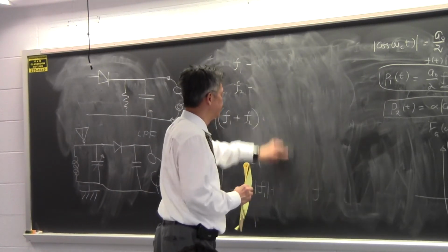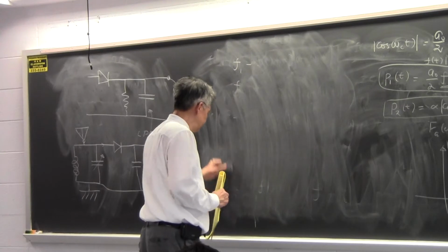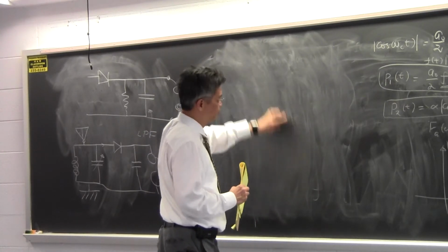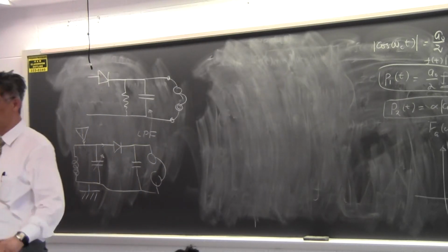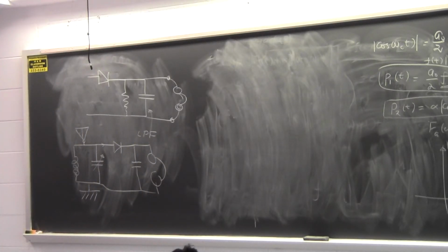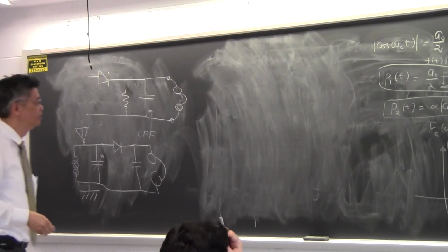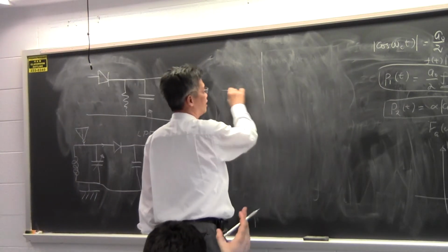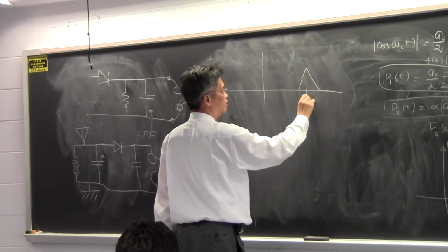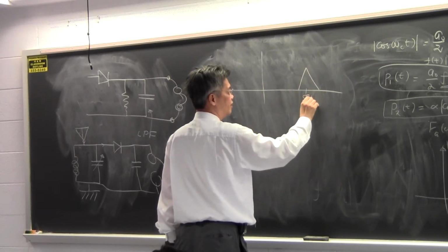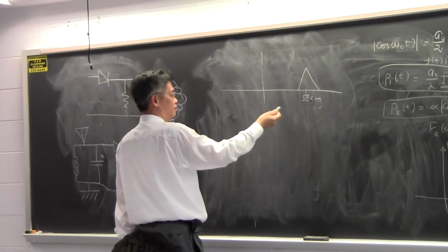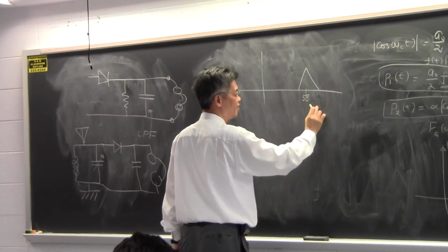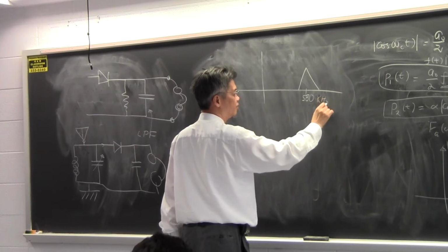If you do coherent detection, you can bring the signal back into the pass band as a low frequency band, but in order to get the signal properly passing through your system, you still need a very high quality filter. So if I have AM580 over here, 580 kilohertz, that means the carrier of the station is 580 kilohertz.